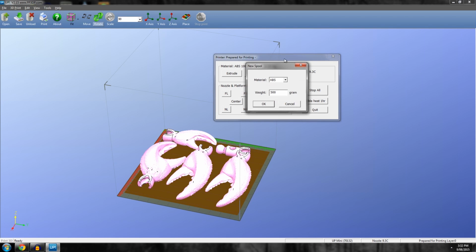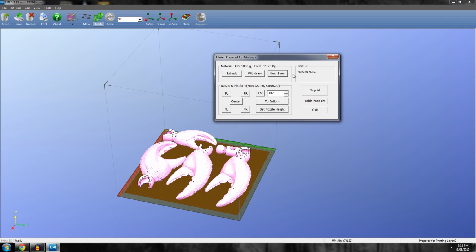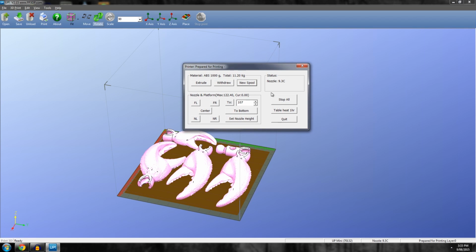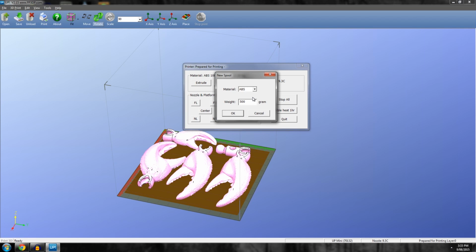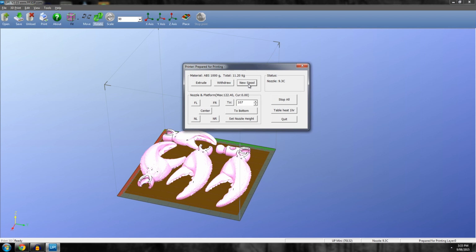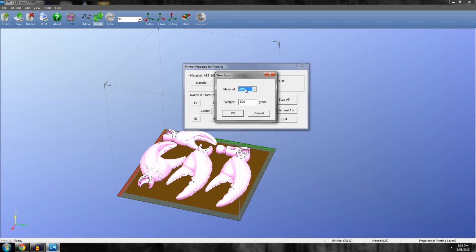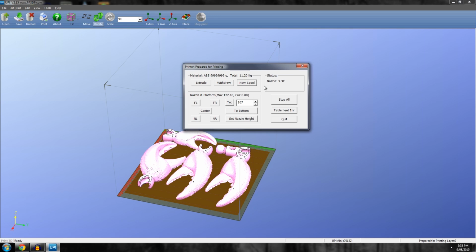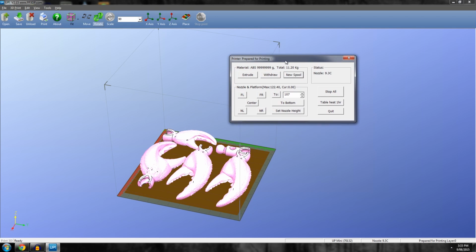So it's actually also worth noting that the Up printers are dumb in regards to if the filament does run out, it's not going to know. So the spool option saying 500 grams, it will try to keep track of this every time you send a print to it. But if you cancel a print or something goes wrong with it and you turn it off, it doesn't really know. So you might get a message saying, oh, I've run out of filament. Would you like to continue? Yes or no? I tend to just hit new filament just to stop that ever turning up and ever annoying me, because it's kind of a flawed system.